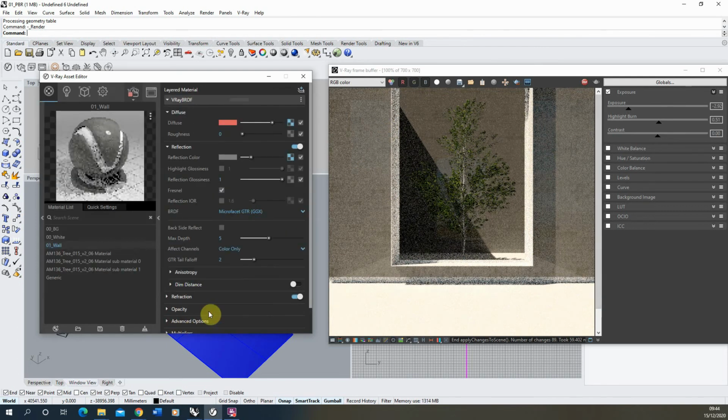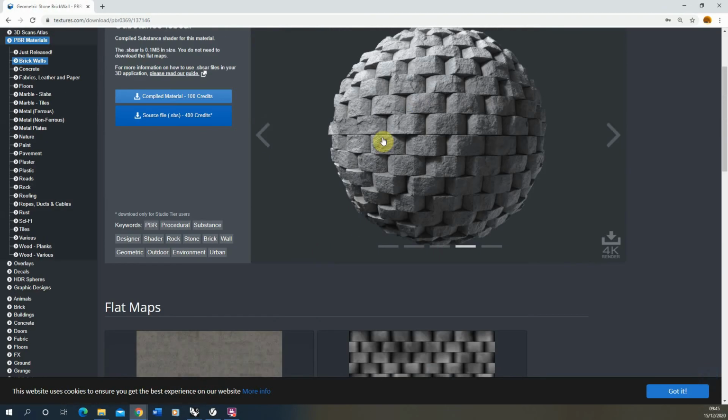And then I'm going to go back to my object. Now the reflection color purely dictates how reflective an object is. It won't control the shininess of the object. That's based on the glossiness value, and you see here the reflections are very sharp, they're very glossy in effect. For my brick I don't want that at all. We want the reflections to be quite muted, and you'll see in this preview there are no sharp reflections on here at all. It's only really picking up subtle bits of light on the corners.